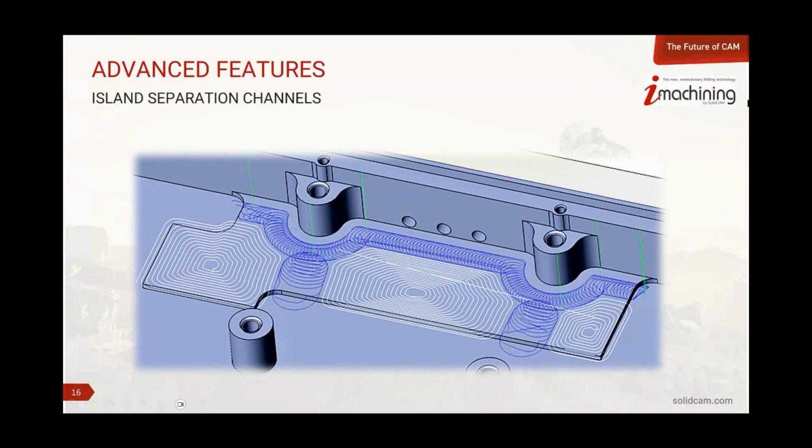And so in a situation like this, one single continuous morph would wind up being rather inefficient, because along the long sides, it would be cutting it very near the minimum cutting angle and just barely taking any material off at all. Of course, across those short sides, we would be closer to or at the maximum cutting angle, where material removal rate is extremely efficient. And this would give us an interesting tool path, because we have an awful lot of the long sides at minimum, and it wouldn't really be as efficient as we would like to see it.